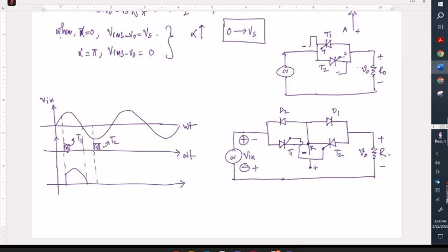Okay. Yes, sir. So in order to avoid two driver circuits for two separate thyristors, we can add two extra diodes and then we can have a common circuit for driving two thyristors at the same time. So in that way, we can avoid the problem of having two separate circuits for turning the thyristors on. Is that clear for everyone? Any problem regarding this?